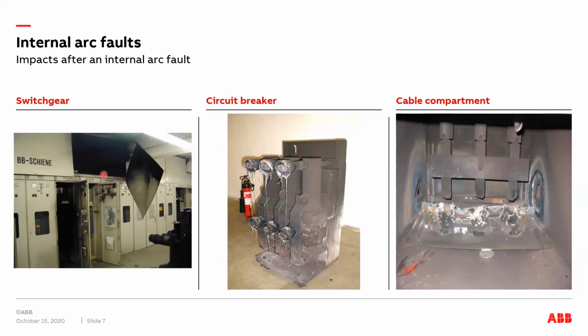So you see quite a lot of damage here. In the middle we have a circuit breaker that has been racked in the closed position. It has been racked out for testing purposes. It has been in closed position and racked in, and by overriding or breaking mechanical interlocks, it has been racked in and getting close enough to busbar with 20 kV and earth. And if you get close enough, you will have a flash over. And here you see that even the tulips have melted off the energy that you have in the flash.